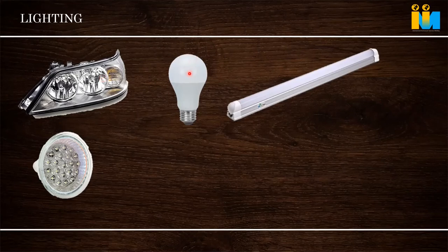And this is the diffuser we were talking about earlier. Transmittance should also be there, but the LED light source should not be visible. Then tube lights: we use the same grade, but this is injection molding, so we can go for a higher MFI grade. But tube light is an extrusion, so we cannot go for a higher flow or higher MFI. Higher MFI means it is more like a liquid, the flow will be fast, so it will not make a thin material.